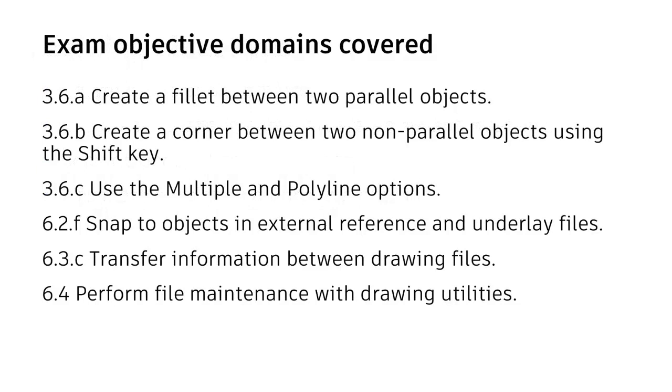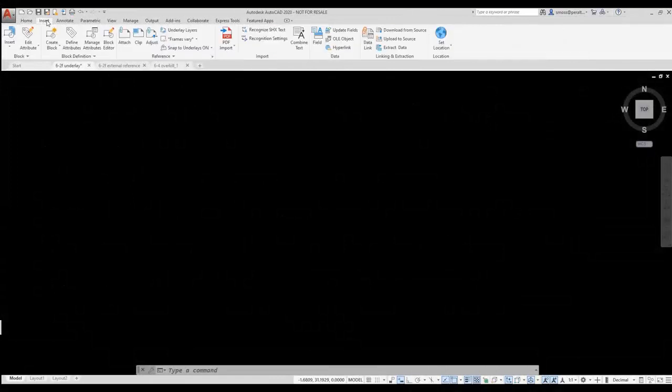I'll copy some drawing objects from one drawing to another. And I'll finish with the Overkill command, one of my favorite tools inside of AutoCAD. Overkill eliminates overlapping lines to help you clean up your drawings. This is especially helpful if you have inserted external references in your drawing, which is one way overlapping lines can occur. To insert the PDF file, I select the Insert tab.